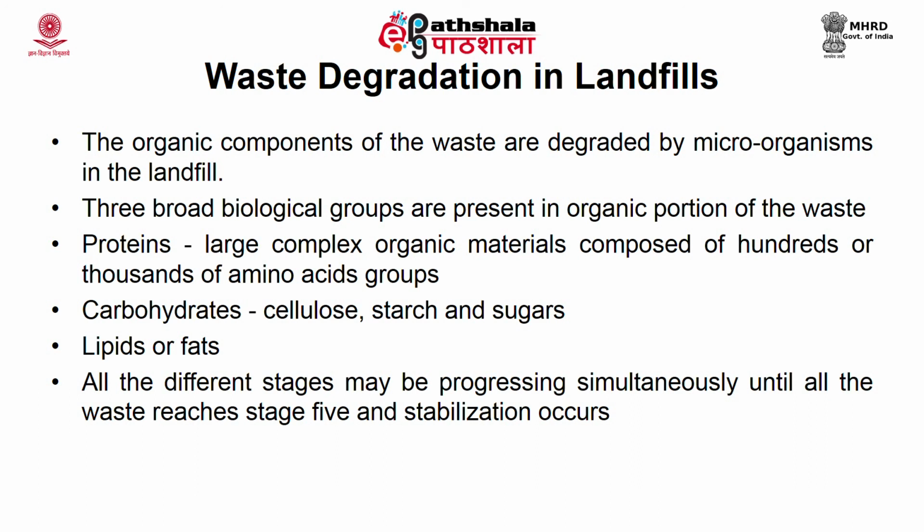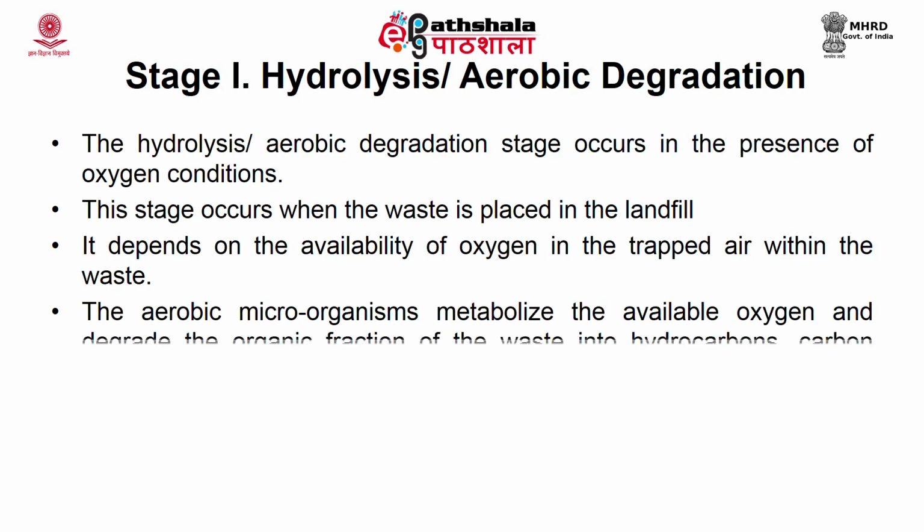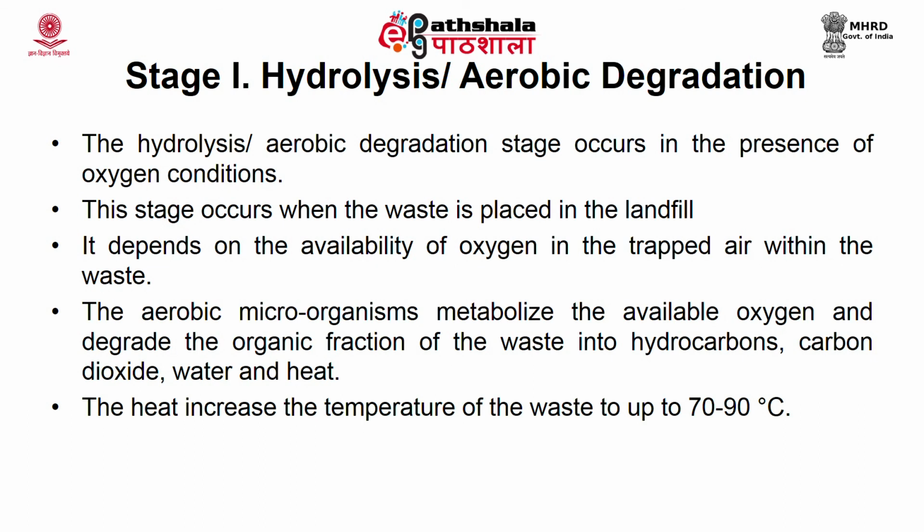So, after aerobic degradation or hydrolysis comes anaerobic degradation, where again you have 4 phases: hydrolysis and fermentation, followed by acidogenesis and acetogenesis, then methanogenesis. Now, the last phase in waste degradation inside a non-hazardous landfill is oxidation. After anaerobic degradation, oxidation takes place, which results in the production of carbon dioxide. Now, the first stage is hydrolysis. See, the waste which comes inside the landfill will be complex.